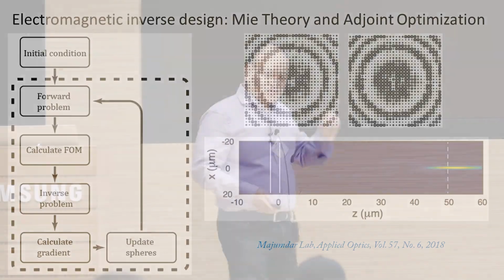Okay? Now, as we are using Mie theory, we are currently limited to either spheres or ellipsoids. We cannot really do it for cylinders because Mie theory doesn't really give you that much benefit. If you're doing the full cylinder, it becomes almost like a full electromagnetics problem. But for spheres and ellipsoids, you can actually get a significant amount of speedup compared to full FDTD.